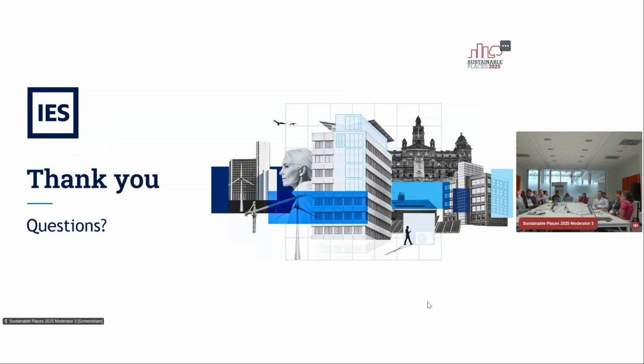You have to take the right data for the year of the measurements for the energy consumption. Closest weather station. Sometimes you can place a weather station on the roof, or you can buy the data. If you have a weather station close, you can just pick it.